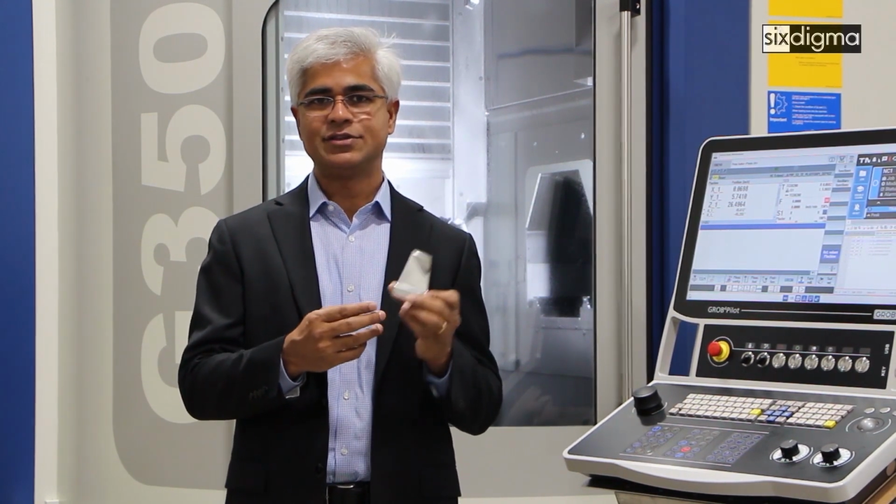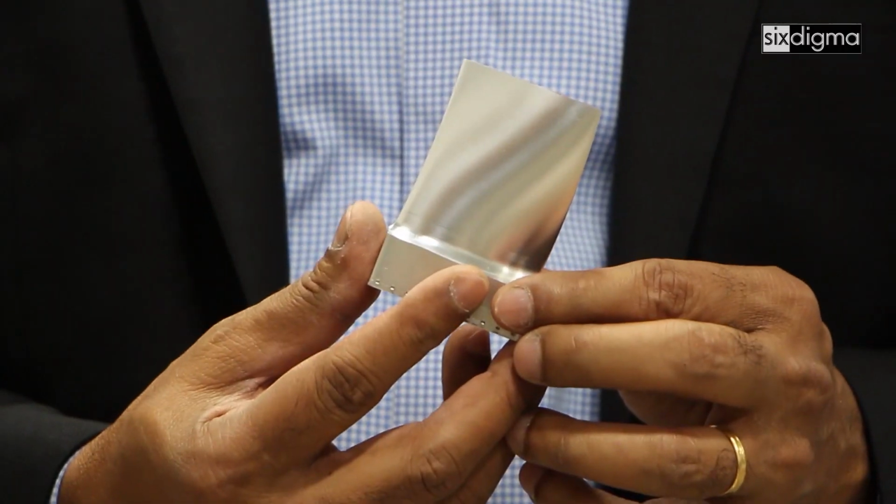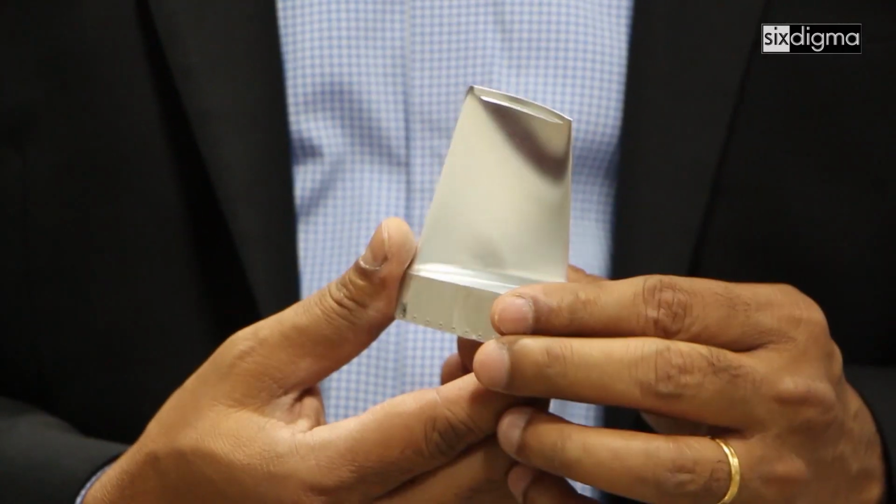Even though this airfoil looks really smooth, during engineering design, various manipulations of these surfaces introduce all kinds of surface imperfections and curvature reversals and other artifacts that make it extremely difficult to machine these parts and produce a really smooth surface on the CNC machine. This, combined with tight tolerance requirements on these parts, makes it an even bigger challenge.